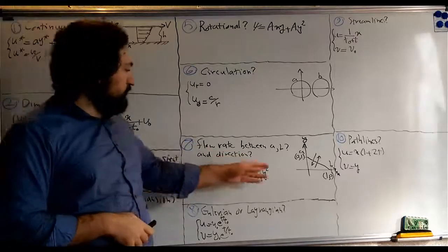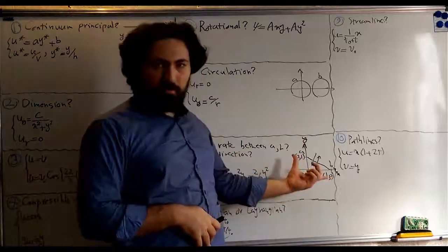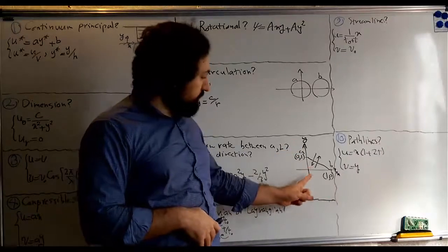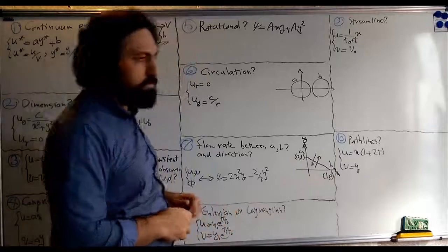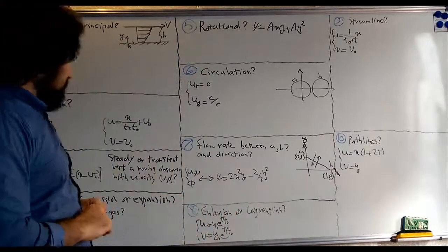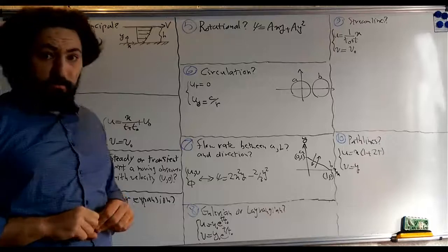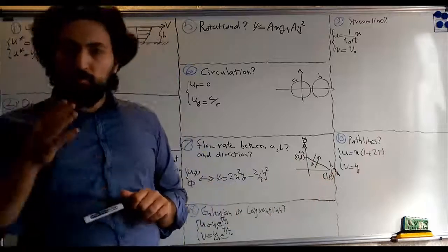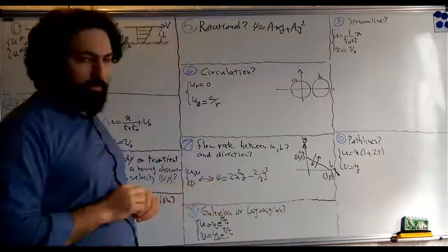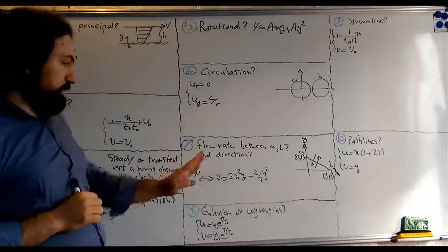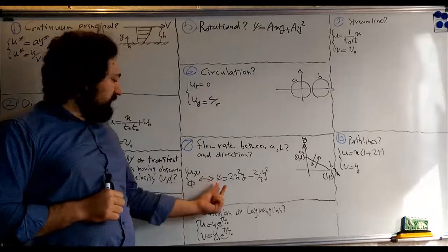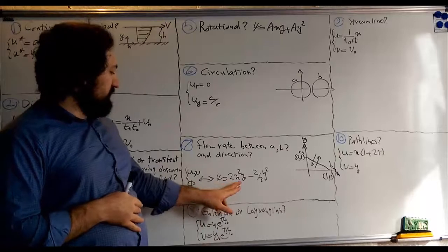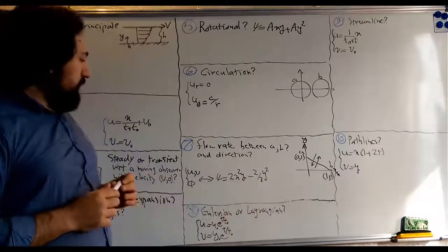So compute the flow rate crossing the area between 2 points A and B. The vertical distance of A from the origin is 1, and the horizontal distance of B from the origin is again 1. So what is the direction of the flow? Which of these 2 arrows correctly shows the direction of the flow? And also compute the volumetric flow rate crossing the area between those points, and the stream function of this flow field is 2 x squared y minus 2 over 3 y squared.